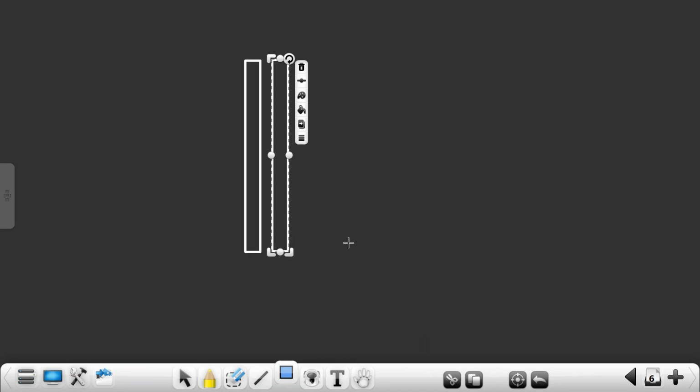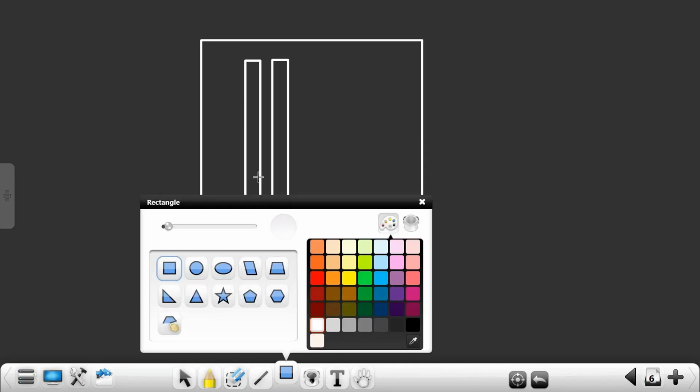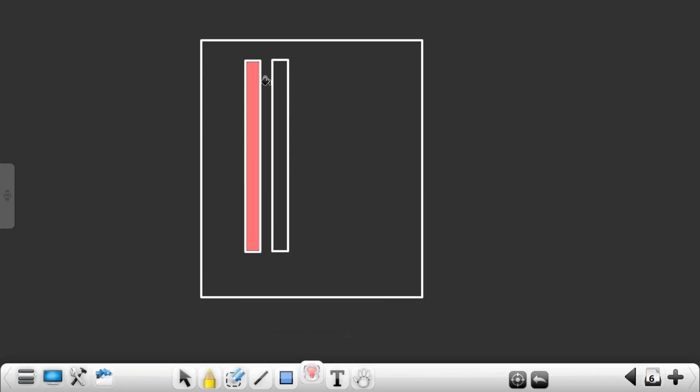So this is the planar metal layer. For example, I have two metal layers running parallelly. This metal layer is formed by a process called etching. Etching means I will have a full metal layer. I cannot create such a small metal layer only in this location, so I will create the metal layer at this bigger location first. Then wherever I want the metal layers, I will cover that region through one mask. Remaining all regions, by using some photolithography method, I will etch. Etch means remove that metal layer.